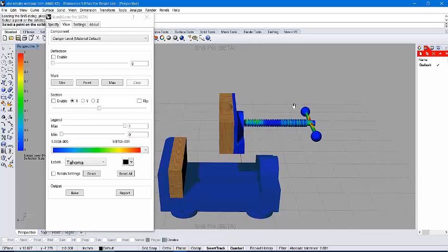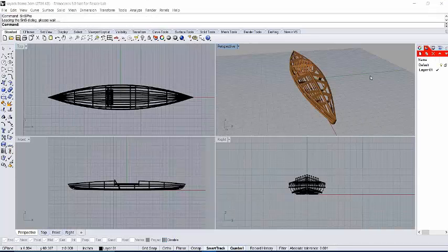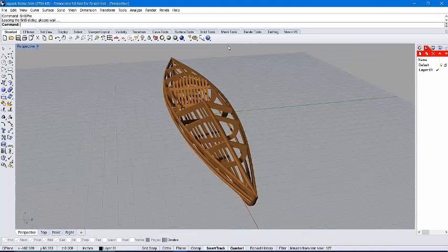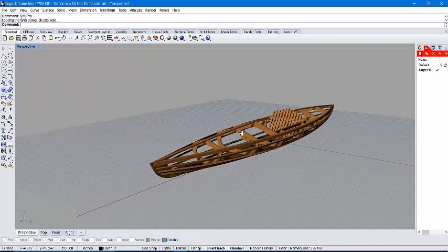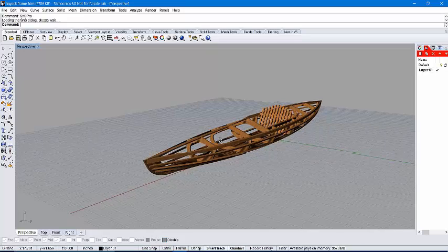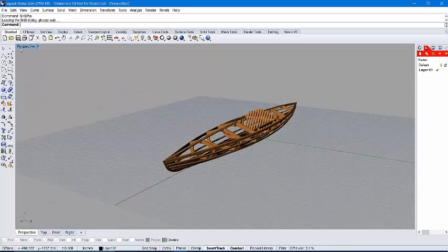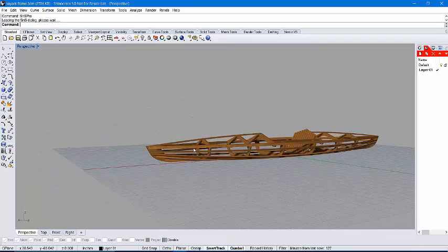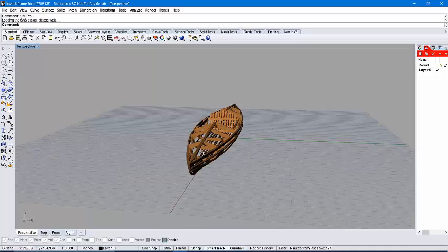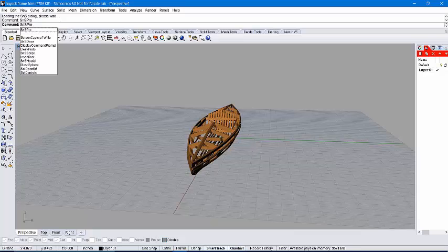I have set up. And now I'll get into a couple more advanced topics with my kayak simulation. So the kayak frame is already built. A frame like this is commonly covered with a nylon skin to be made into a kayak. So what I want to simulate is how this wood will react when a nylon skin is covering the wood and applying that compressive force. So I'll start by opening up Scan&Solve Pro. And the scenario selector is once again opened.